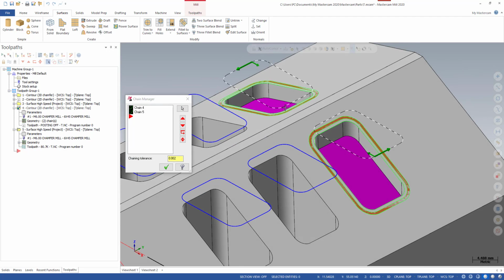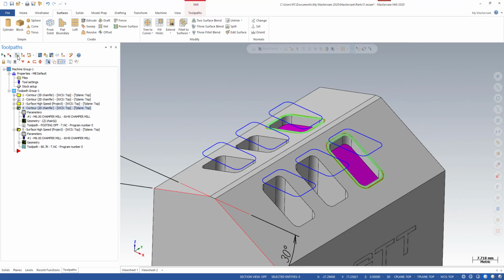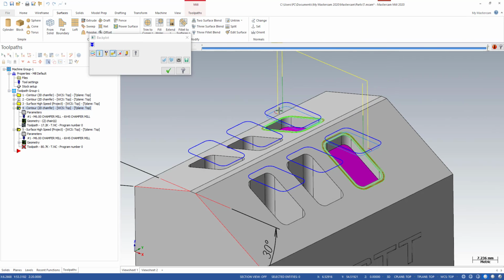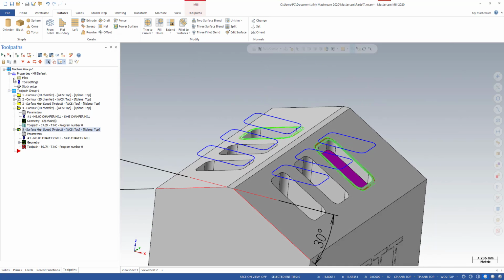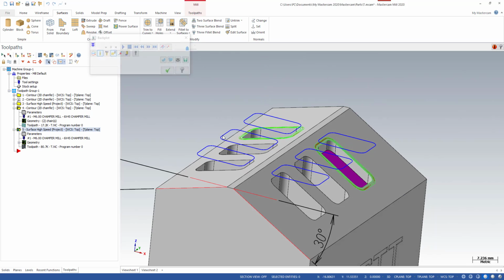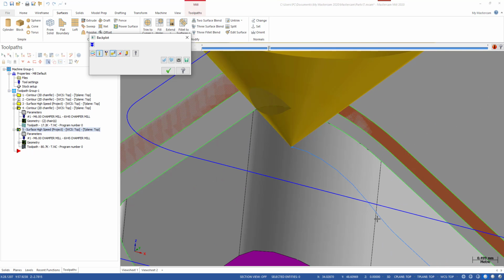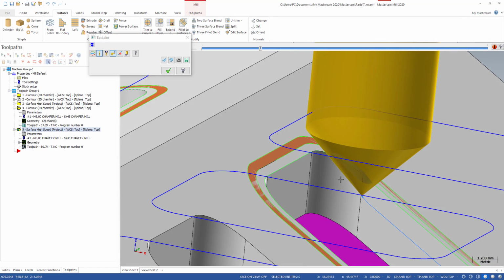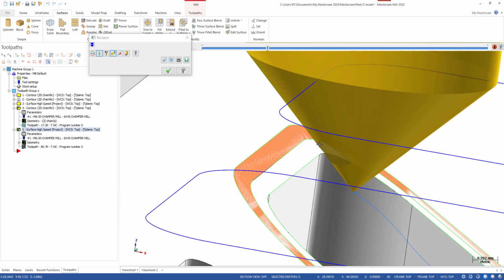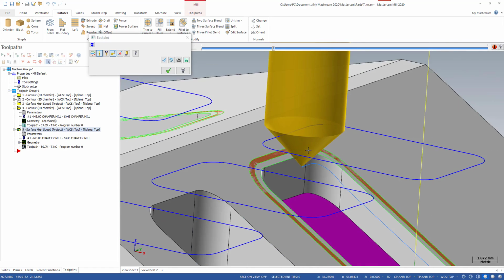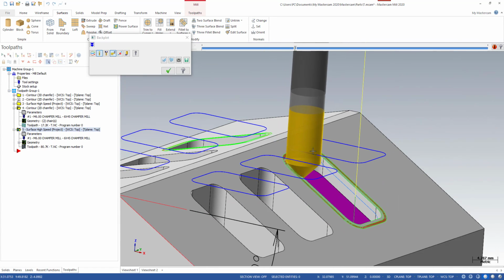We have two chamfer, 2D chamfer here. Oh, I need to unghost it, and we use these two chamfer for this projection toolpath like this. Very simple. Very smooth, right? You can see when the tool goes here, it automatically goes up to follow this control surface. That's the key how we control the width of the chamfer. Very easy, and that makes sense, right?